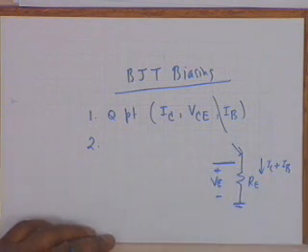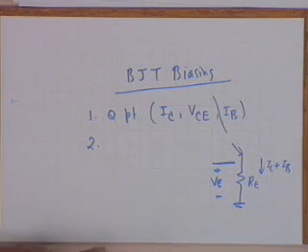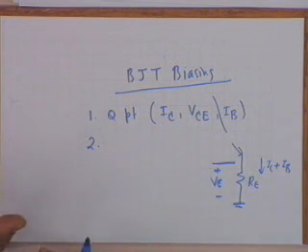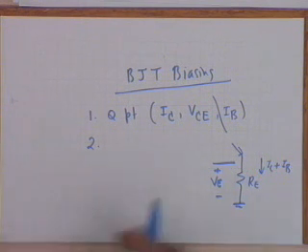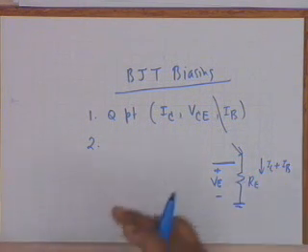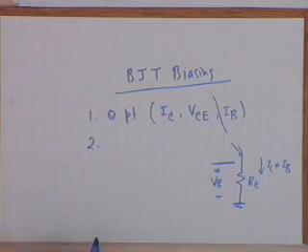Suppose your power supply that is given is, let's say, 12 volt. Then obviously Re cannot drop how much? It cannot drop 12 volts because there would be a VCE, there will be a drop in RC, and you don't want this drop to be large because you want a large swing in the output voltage. Typically this is chosen about 20 to 25%, rule of thumb again, there is nothing sacred about it.